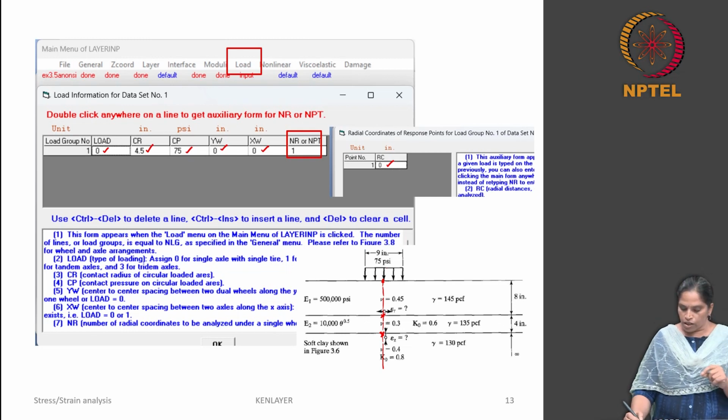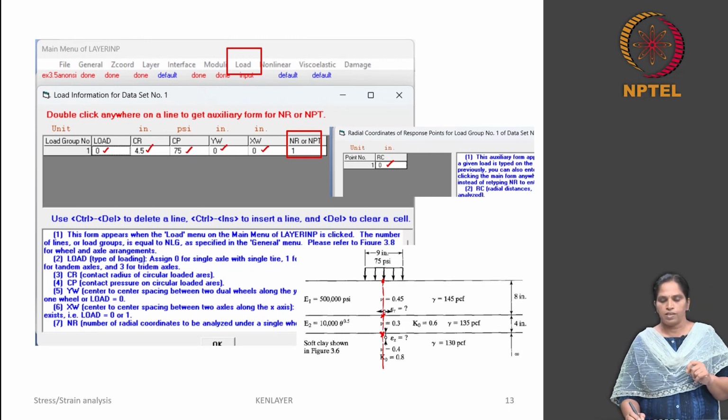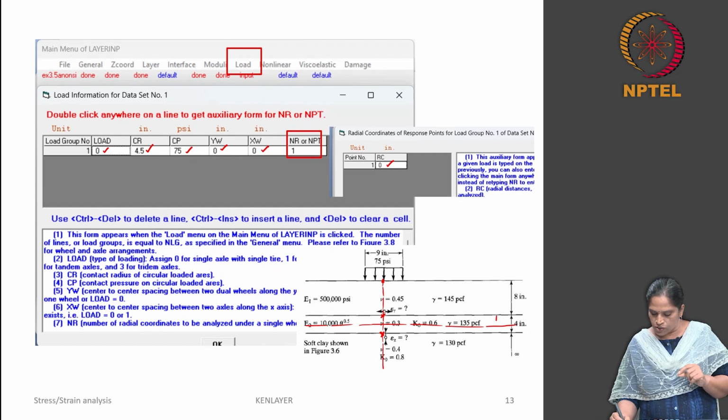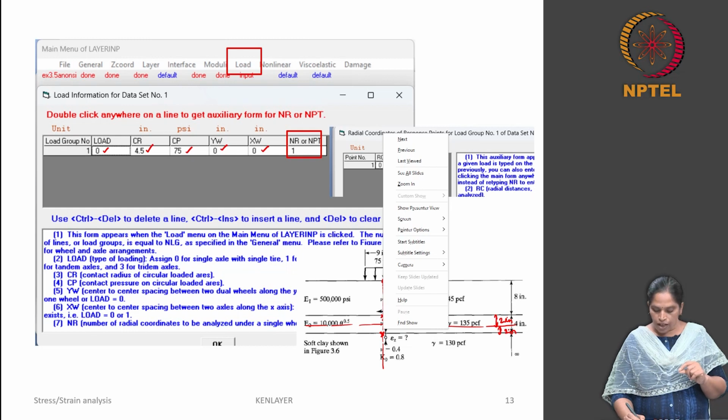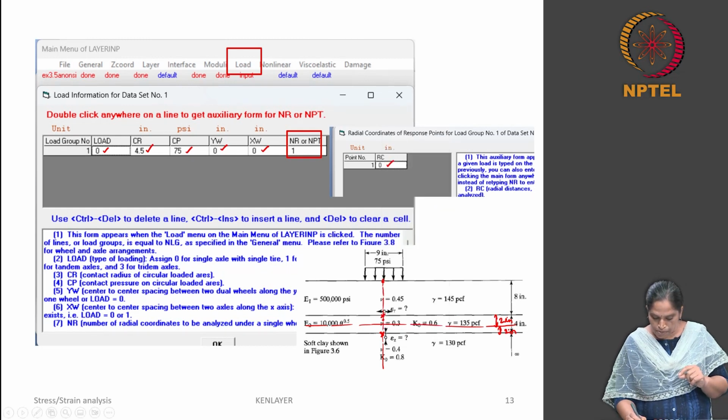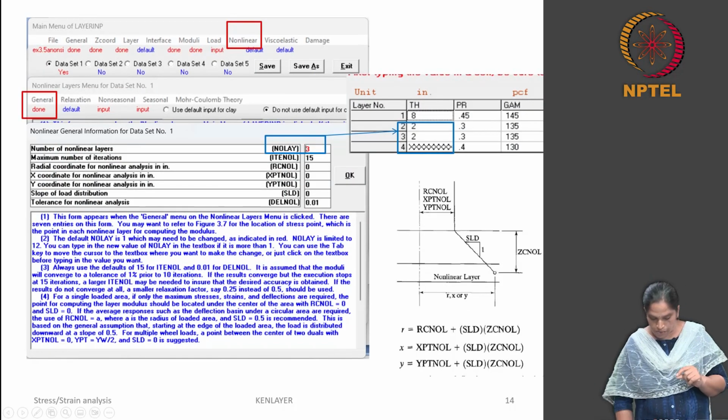This modulus is computed using the first method, that is, by dividing this base course into two layers, each of 2-inch thickness, and the mid of each layer is defined as a stress point. The modulus values are determined from the mid of these layers.